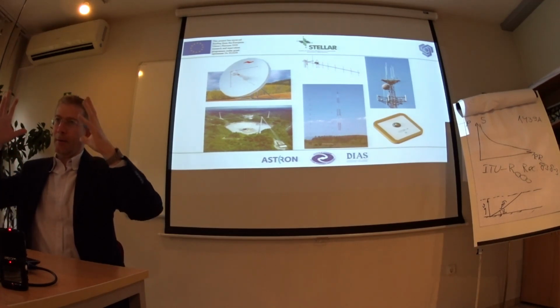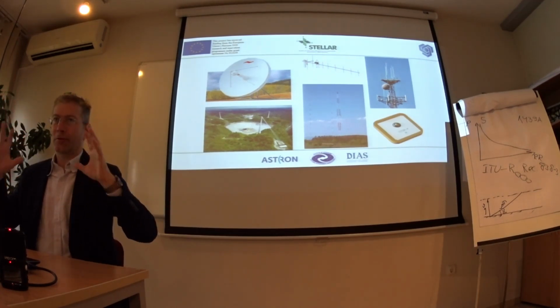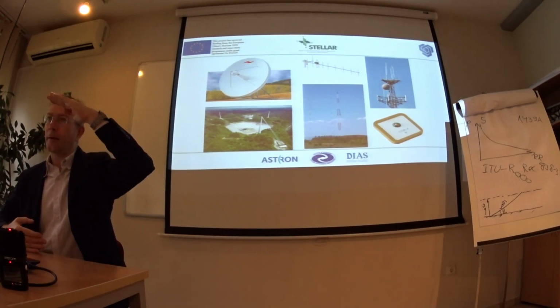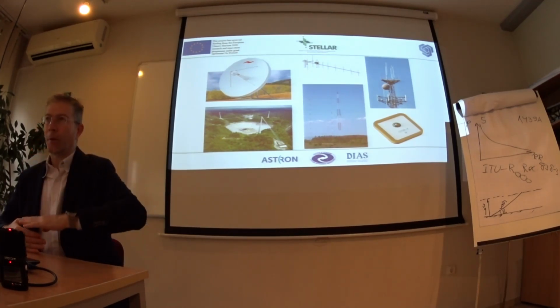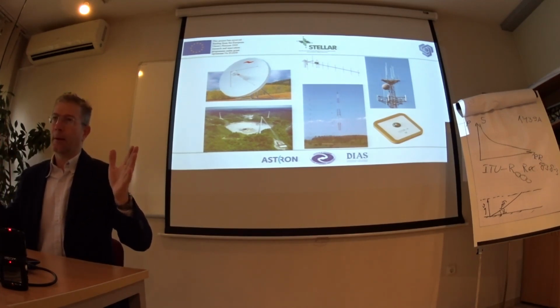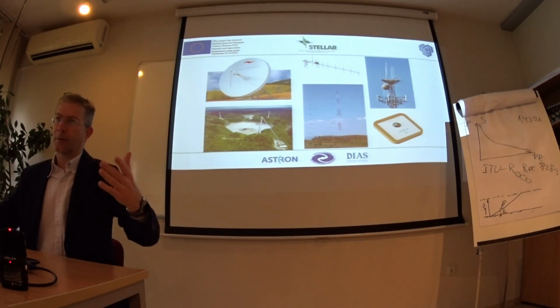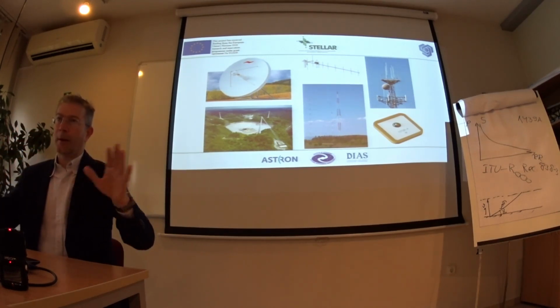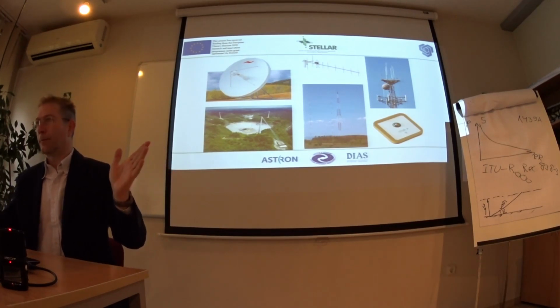The white boxes are just enclosures, and inside there is an array of dipoles which form a non-directive pattern in the horizontal plane and a directive pattern in the vertical plane, and cover 1/3 of the base station cell.